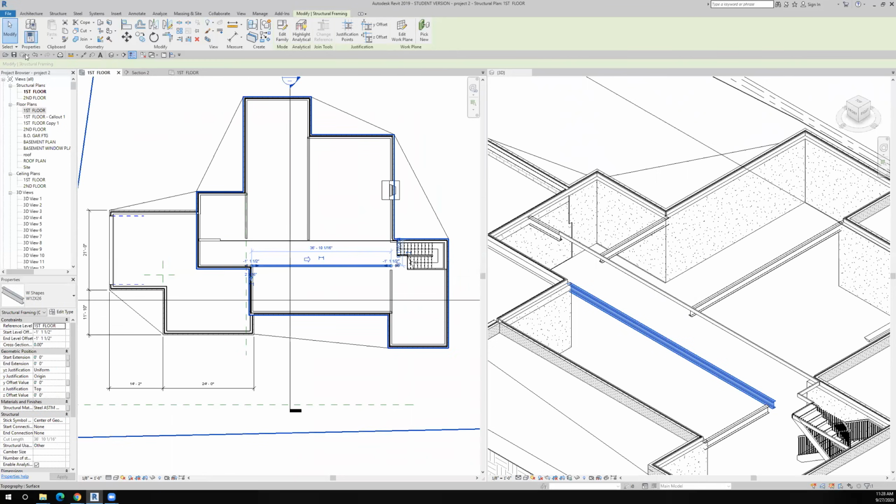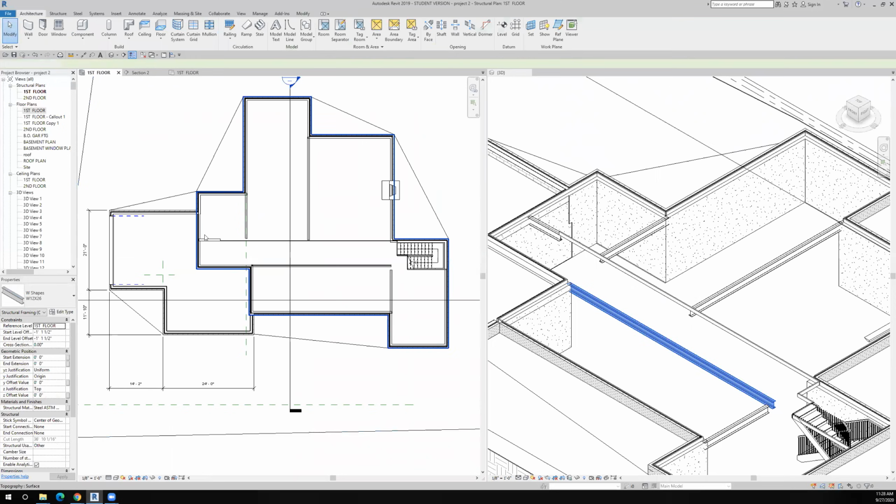And the reason I want to do that is I want the entire span of this particular part of the floor, of the floor of the foyer and the back hall, I want that to be in the same direction. So there won't be any differential movement between the two different spans, which might crack a floor.